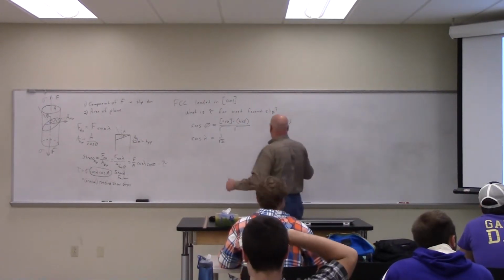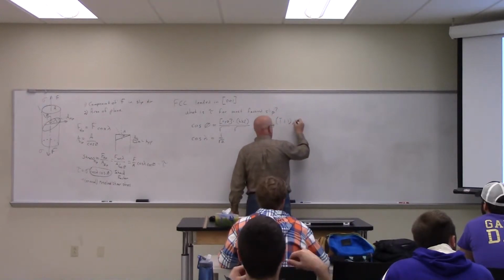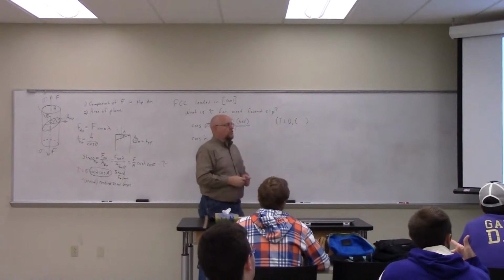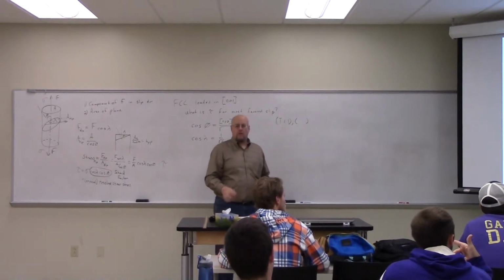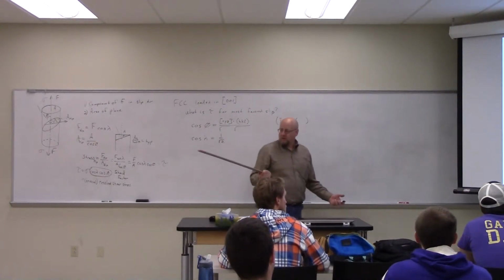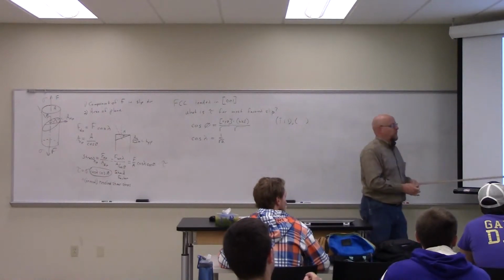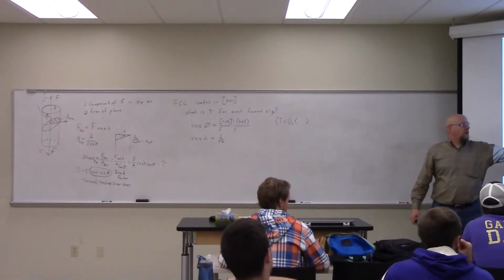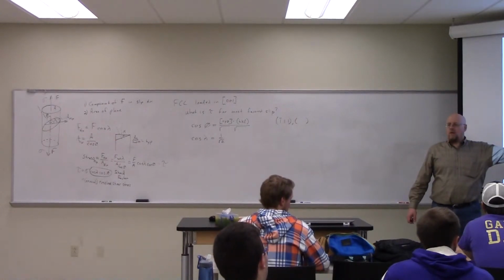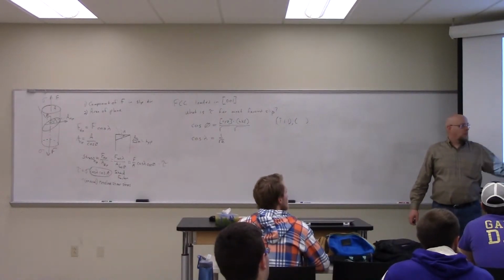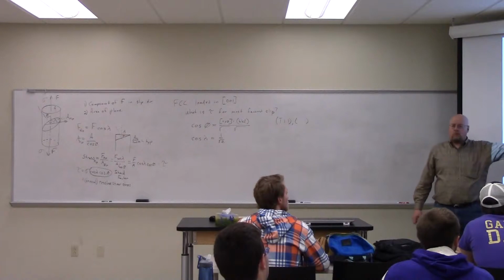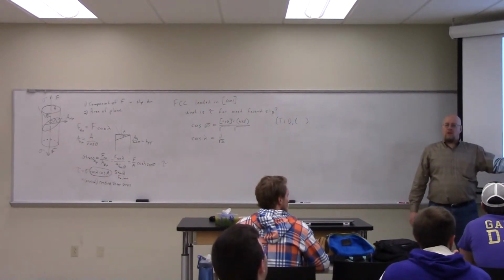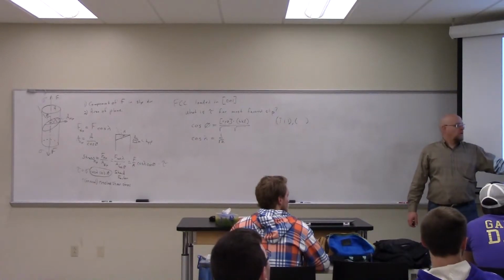And what's that plane? 1 bar 1. What are you going to choose as your origin to determine the plane? The back corner, we choose that one, right? The bottom right hand corner in the back. And remember, A is positive to the right, B is positive into the board, C is positive up. So 1 bar, 1 bar, 1.